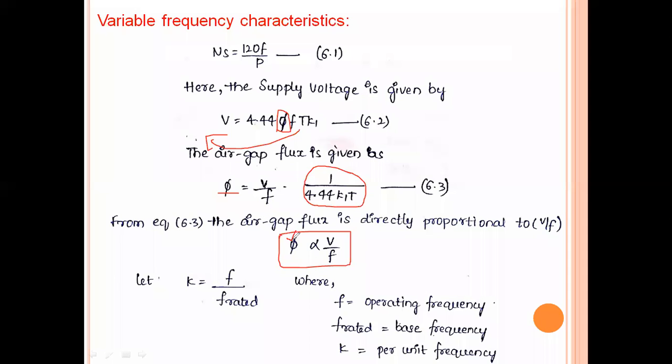Because of the high magnetic flux, the machine goes into saturation, and then the machine performance will be completely degraded because of uneven currents, uneven torque production, and uneven AC voltage on the windings, which will distort the complete performance of the induction motor.